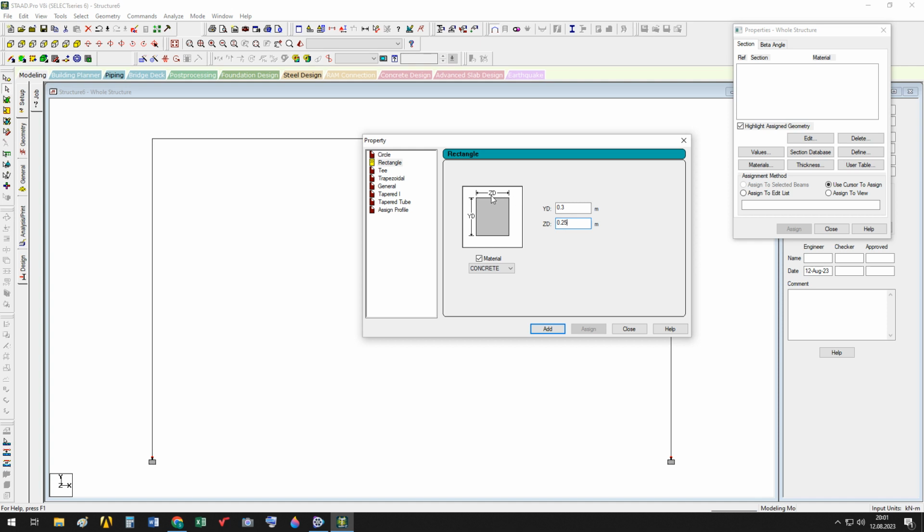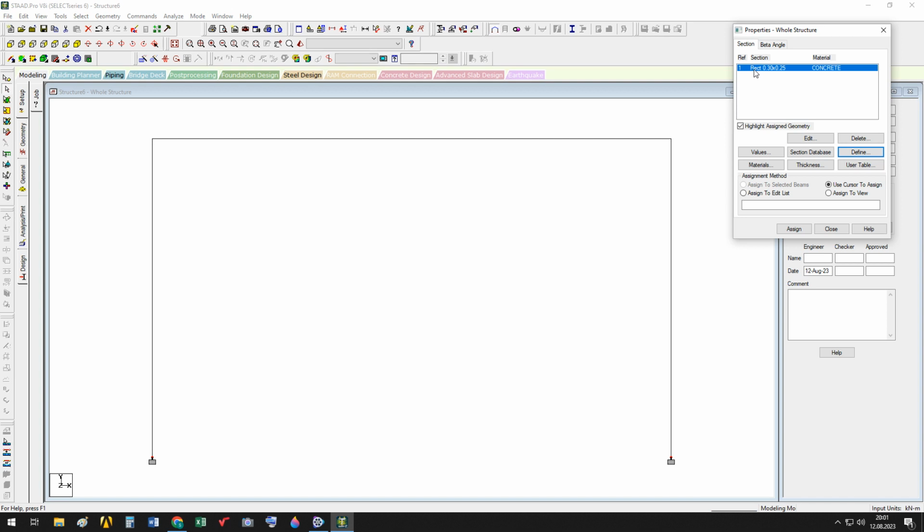These are also the local axes of the frame members. Here in Staad Pro, it's called beam. Its material is assigned as concrete. I will not change it, and I won't speak about how that is done in this video. Now you see, using the property page we can quickly create a cross section, choose a cross section and its belonging material, and then click add, close, and I have to assign these two properties to the beams.